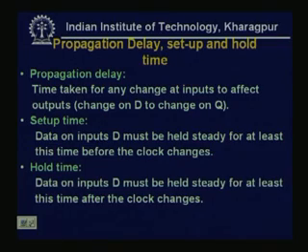Say if we consider one D flip-flop, then a change on D will affect the change on Q. The time taken to propagate this effect from D to Q is the propagation delay.